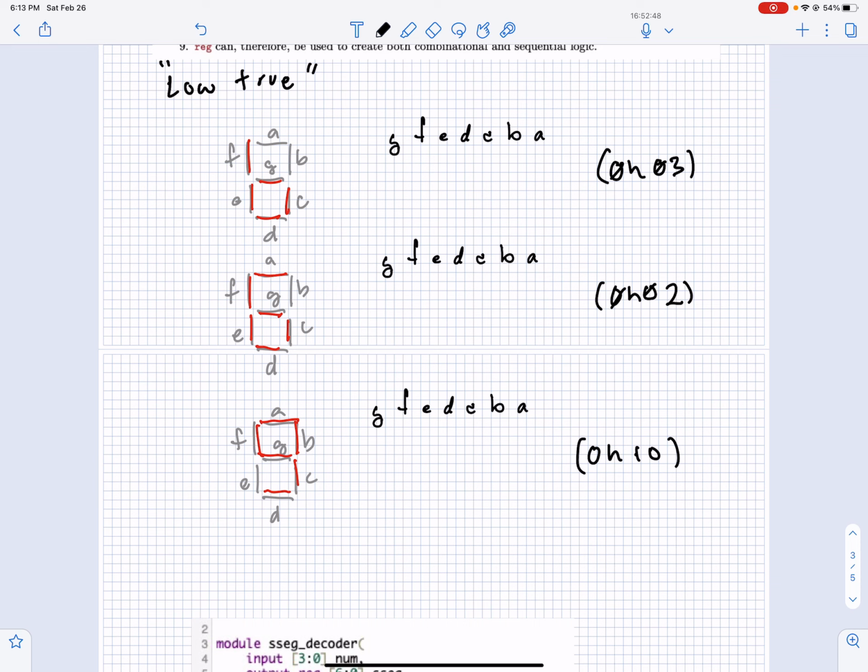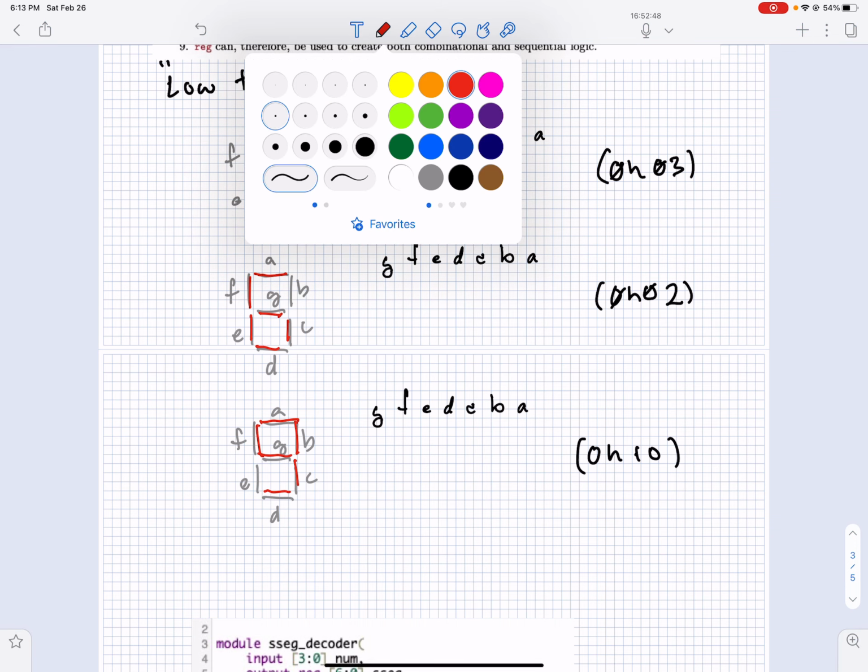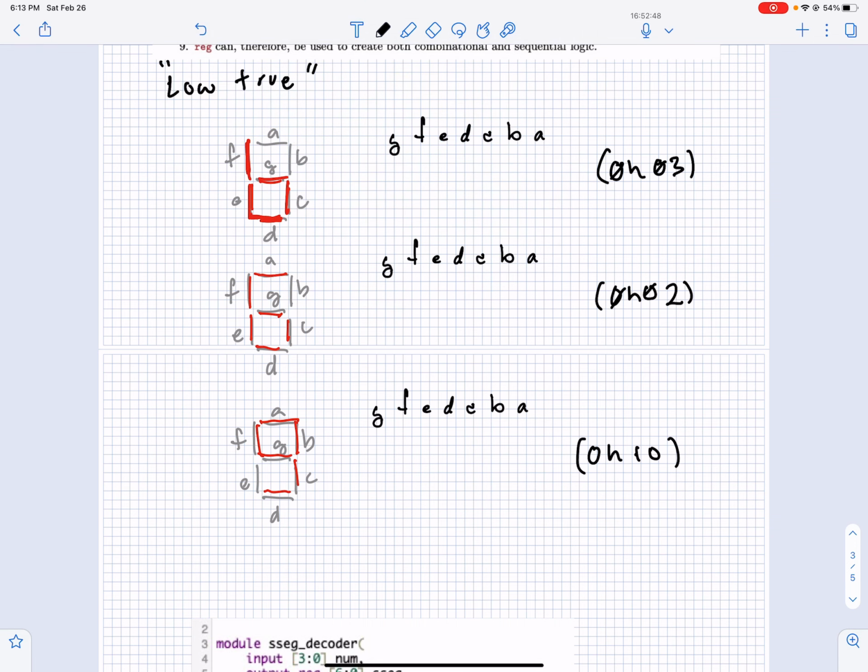All right, so what I've got showing here is an example. Let's say we wanted to make a B. What our hardware is trying to do is to take data. So how would we represent B? B is 1, 0, 1, 1. And we want to take that and turn it into a bit pattern that represents the letter B in a 7-segment display. So I'm looking at this, the places where the LED is lit up, the part that I'm showing in red, should be a 0.